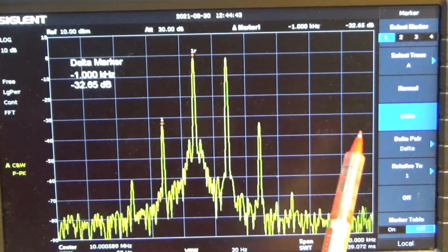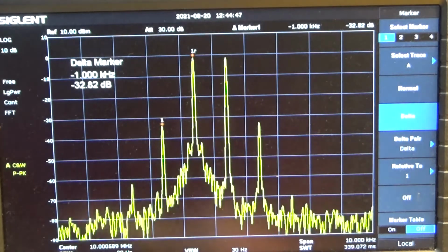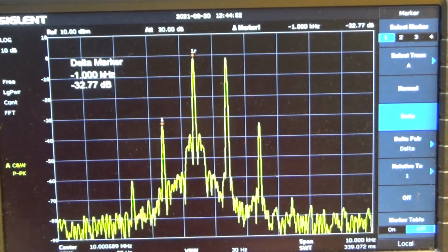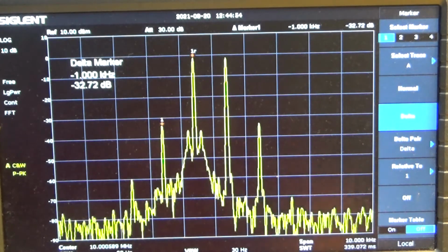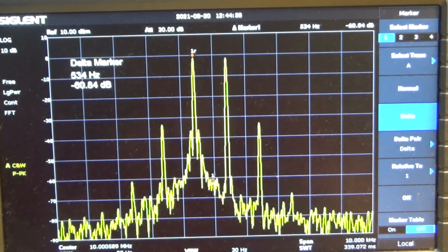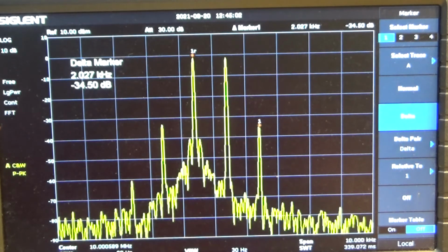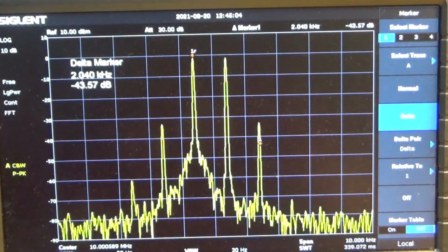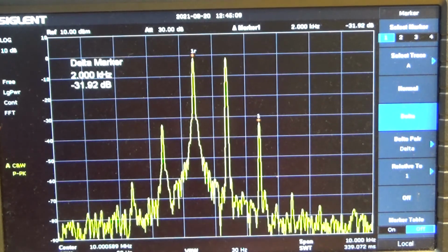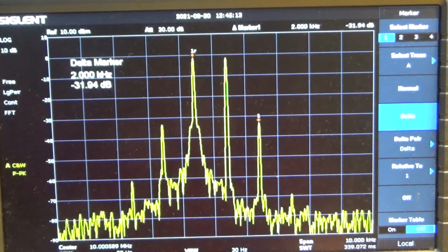If you had a strong medium wave or long wave signal, something that's 30 dB down on that is still going to be quite audible. It's going to be quite a strong signal, in fact. And also, of course, you can go to the other one on the other side, and that one will be 2 kilohertz away, and again 32 dB down on the fundamental.